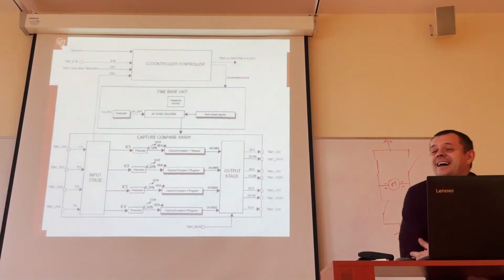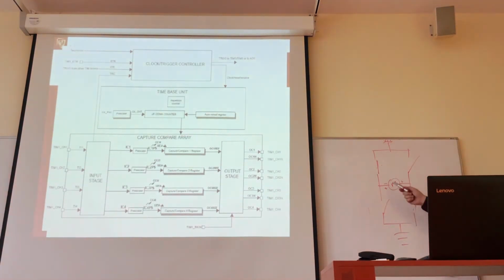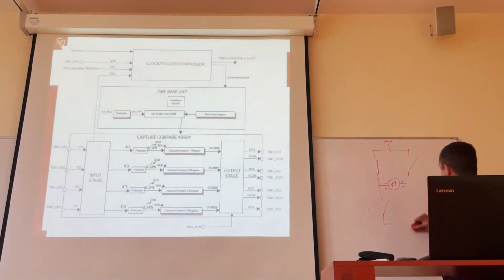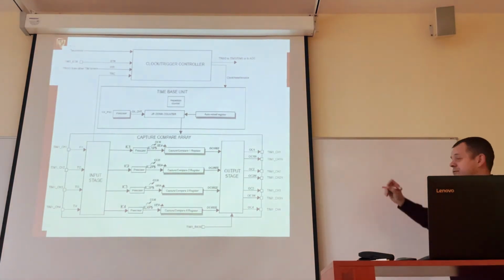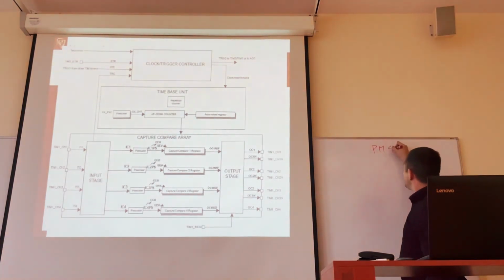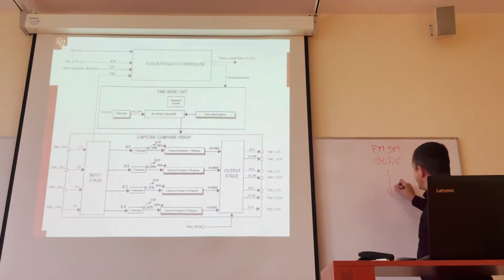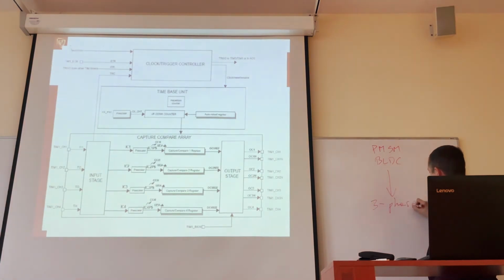No one. Of course, this is driving the DC motor in such a way, because a DC motor has just one winding. But today we are mainly using direct drive motors, which are today PMSM or BLDC motors. They have in common that they are three-phase motors. They are all three-phase motors.